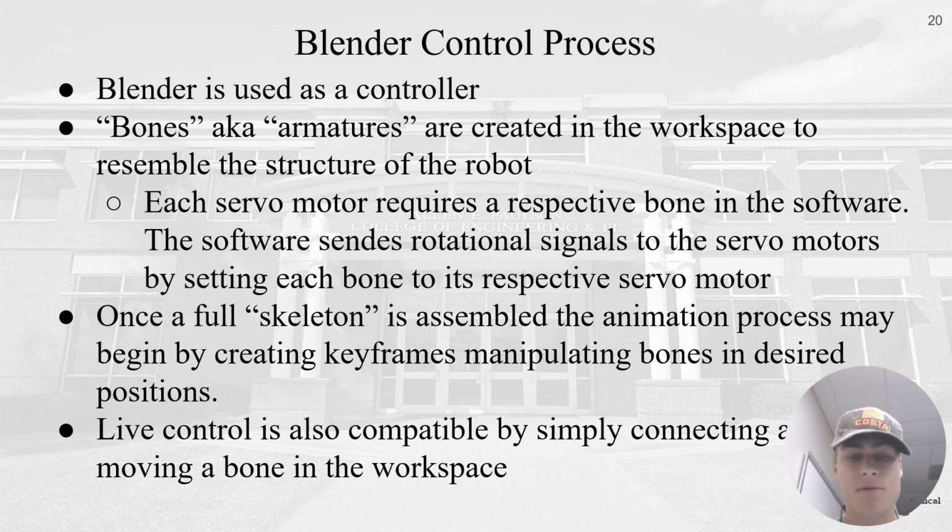So I ended up just working with the teams, Mason and Sean specifically, and we ran through the whole process together and looked at how to build a full assembly, how to upload an STL file, and add these bones within the STL file that correspond to each servo motor. And with that correspondence, you can manipulate the full assembly within the software, and it'll move the respective servo motor on the actual robot itself.